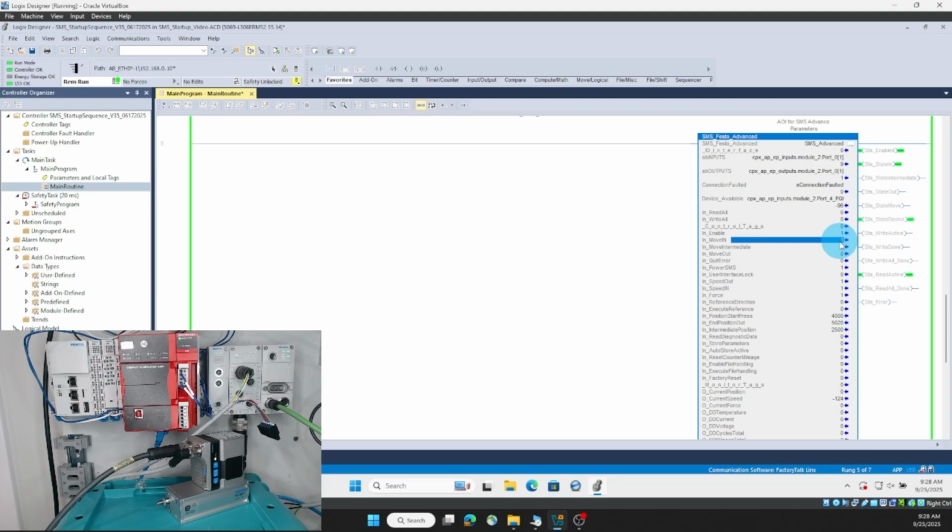That kind of motion can be unexpected. So now let's implement the startup AOI to overcome that initially so that when I tell it to move out, it's not going to perform a reference move, and instead it's just going to only move out, which is the intended motion.